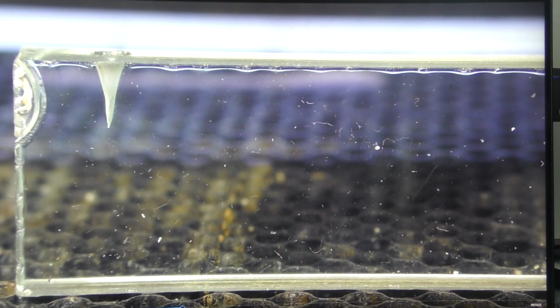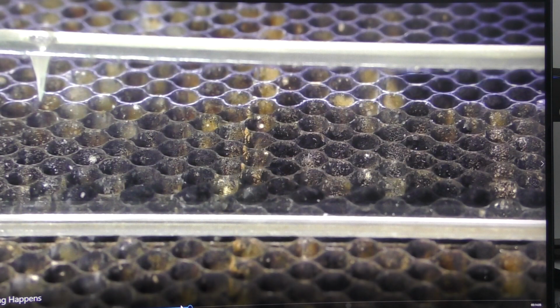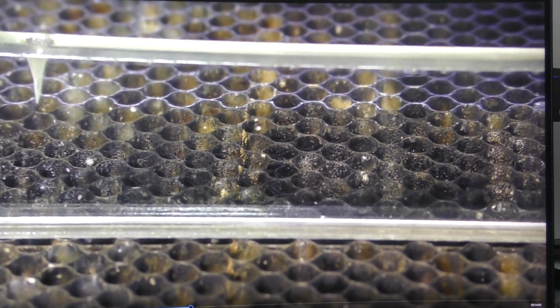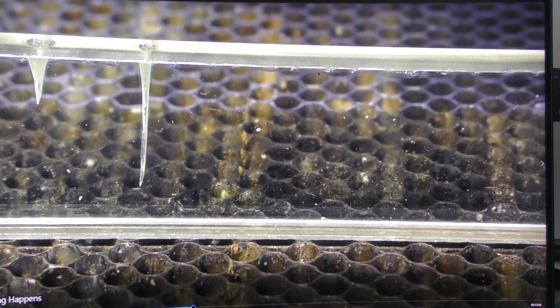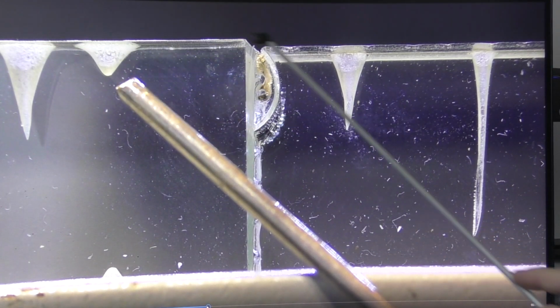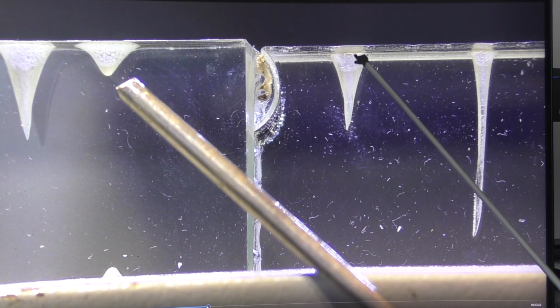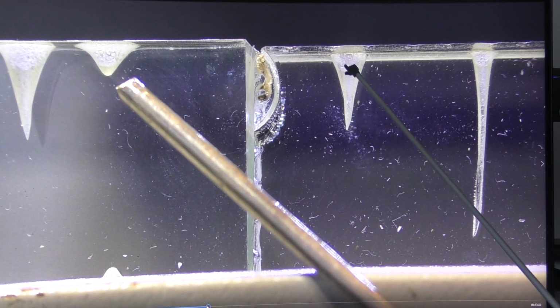So here's what a 1 second burn looks like. Now I've set the distance between the lens and the work to roughly 2/3 of the focal distance, about 120mm. And here's what a 1 second burn looks like 2/3 of the way to the focal point. Now that's a 1 second burn. So that's a burn with the raw beam, and it's 6mm diameter. This looks like about 4 or 5mm diameter, part way down a 190mm focal length beam. We're effectively sampling the beam part way down.